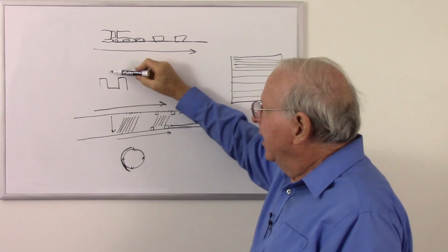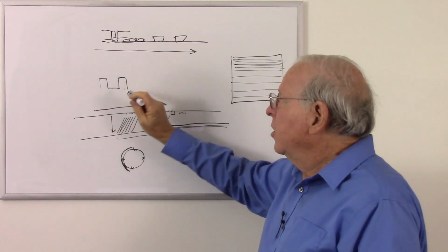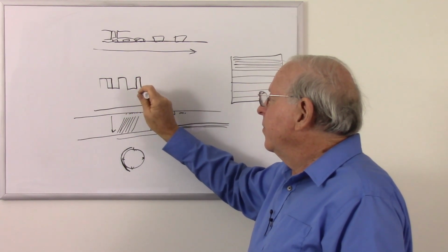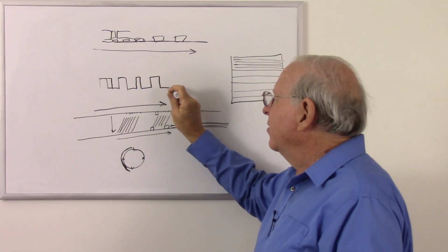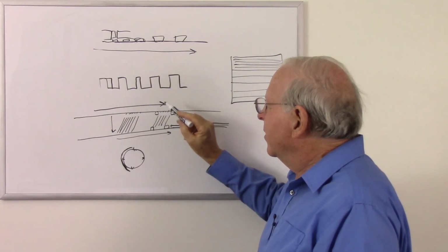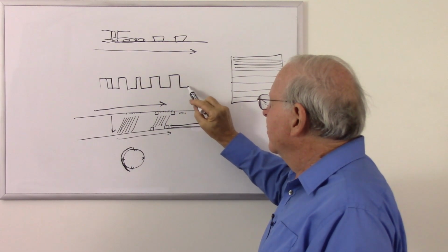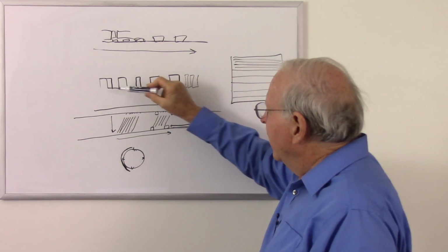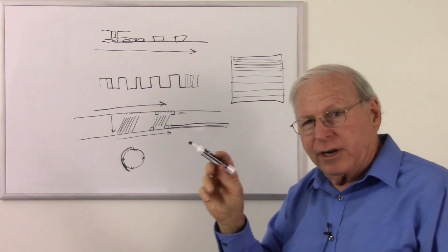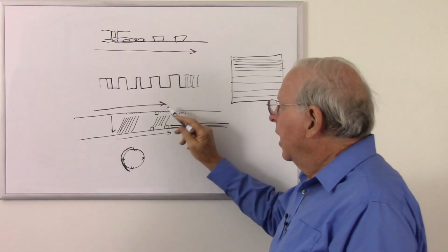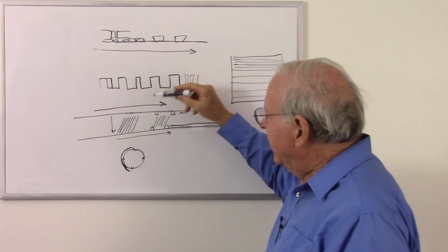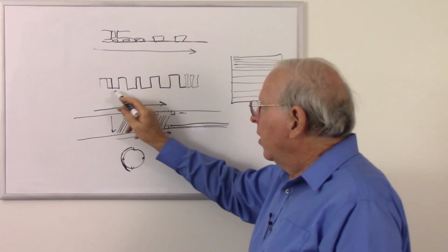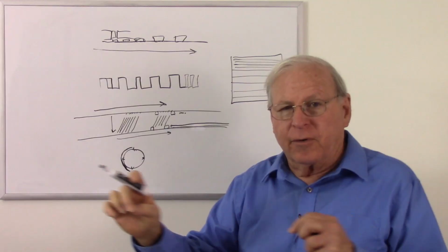But basically it was a self-clocking code where the width of the bits would tell you whether it was a 1 or a 0. Not quite so straightforward. For example, this would be a bunch of zeros, and this would be a bunch of 1s, and because of the way it encoded it, it would be self-clocking, so we didn't have to have any synchronization between the tape and the system's writing or reading it. And so no matter what speed you ran the tape through, it would be able to read the signal.